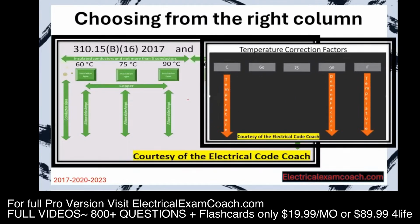Let's talk about choosing from the right column. Just like with bundling adjustments, 99.9% of the time, we're going to be choosing from the 90-degree C column for our starting ampacity. And then we have to make sure that we choose from the 90-degree C column in our temperature correction factor table. In the event of it not being listed there, we're likely going to choose from the 75 if it's listed there, but we have to make sure that we choose from the 75 over here as well. But that would be under very rare circumstances when you are in the testing center. But I just want you to know about it just in case.